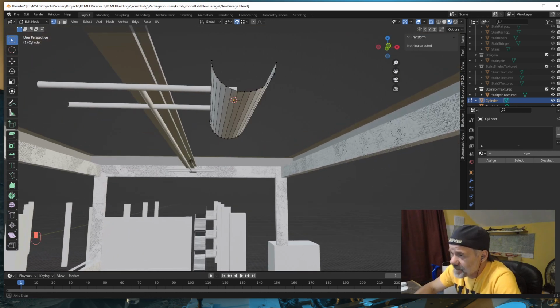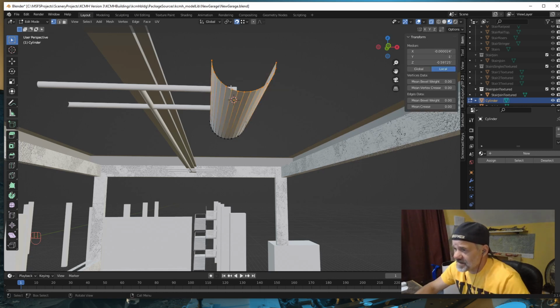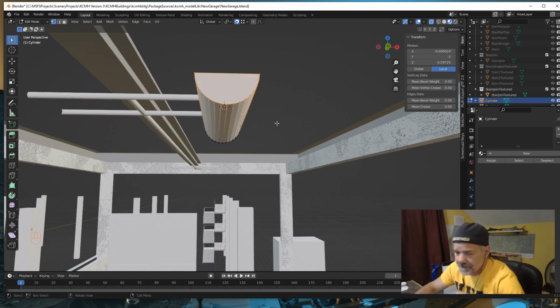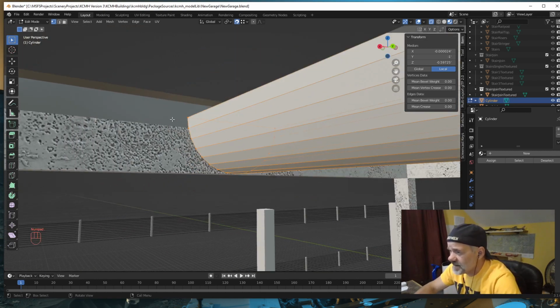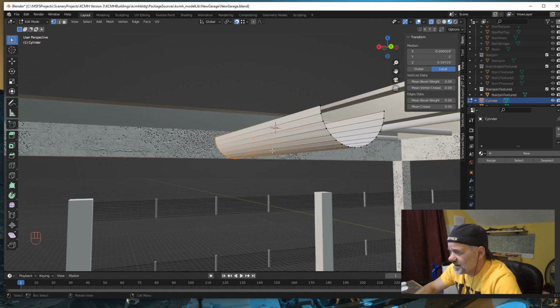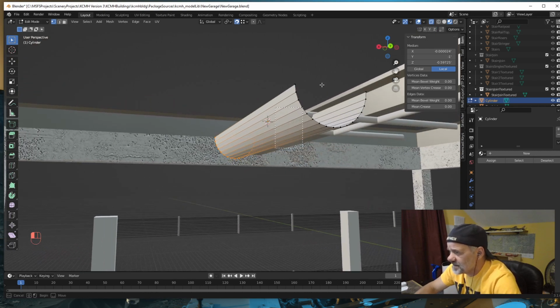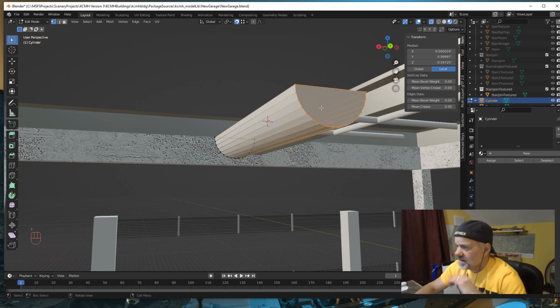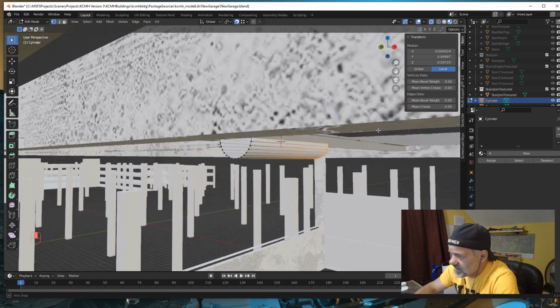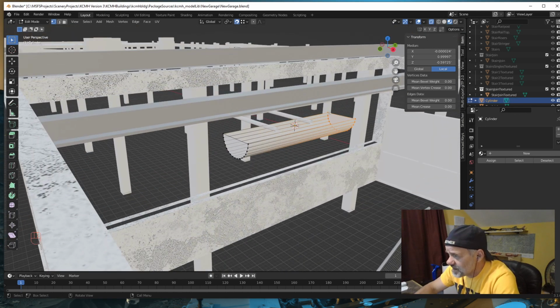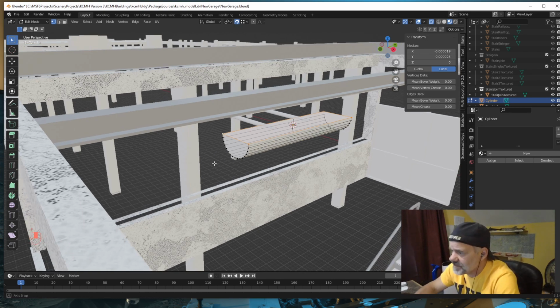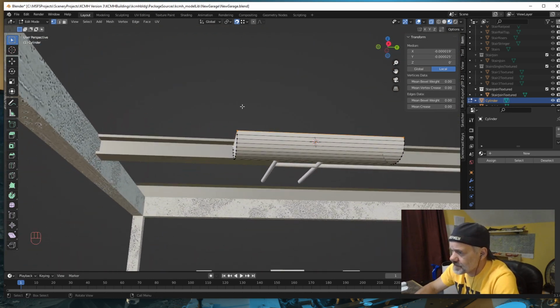All right. So we have that. Now I want to close the ends in, so I'm going to select those vertices, hit F, and then do the same. I hit the period on the number pad to focus in on my selection. Alright, so I have that, and then, even though we will probably never see them, I could select these 4 and put a face on the top too, like that. Let's do a save.